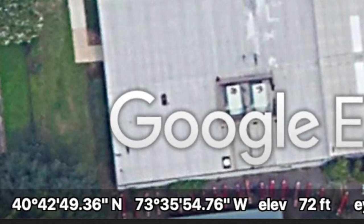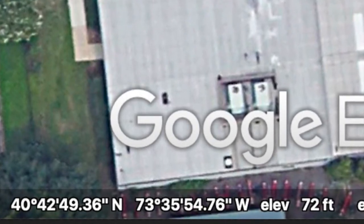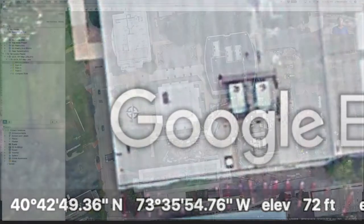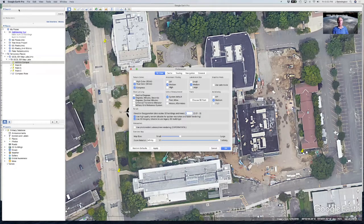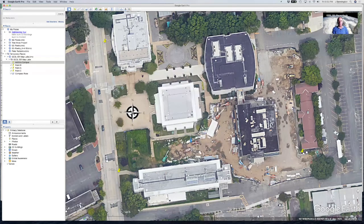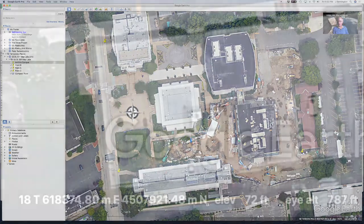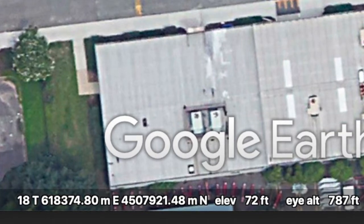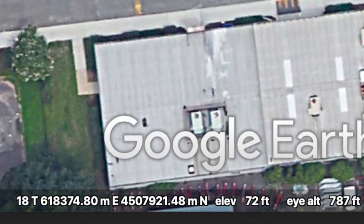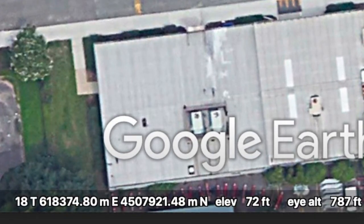Degrees shown with a little circle, minutes shown with a single tick mark, seconds shown with a double tick mark. Now if we go up to Preferences, or again in Windows it'll be Tools and then Options, we can change the coordinate system to Universal Transverse Mercator. And if we do that and position the cursor in the middle of the compass rose, now what you see in the lower right is a series of numbers that reads 18T. 18T is the particular rectangle, it's called a grid zone, that these coordinate systems refer to.